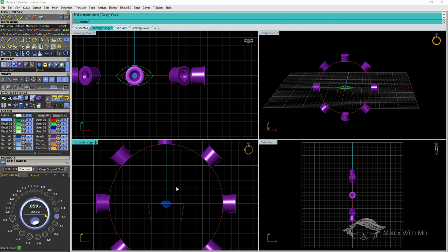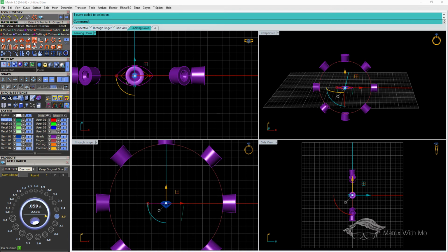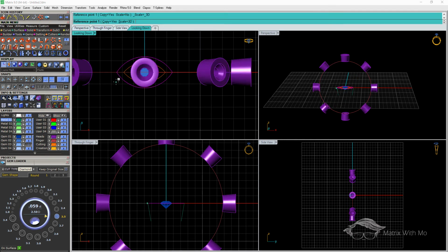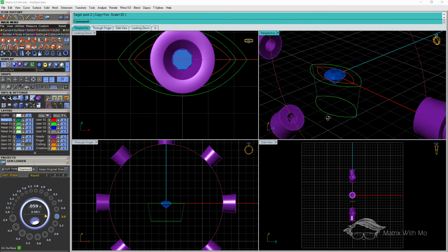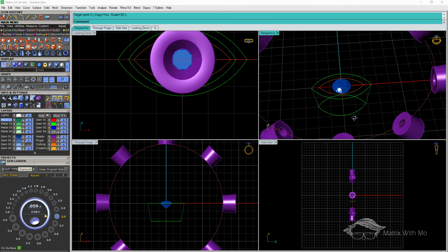And then I need to drop this down in between these 2 points. And so I can use one of my favorite tools for that under the transform menu, orient 2 points. And I want to orient from there to there down to these points at the bottom here. Okay, so that's easy. And then from here I can do a loft. You could also sweep this if you want, but loft is fast.